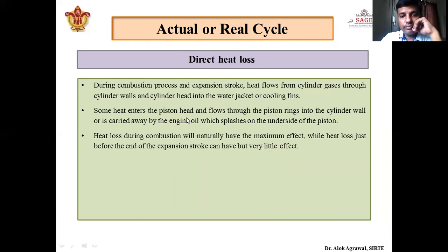And this heat loss at the starting of the power stroke or expansion stroke has the maximum effect, while the heat loss just before the end of the expansion stroke, when the expansion stroke is about to end, has the minimum effect on the overall output of the engine. At the beginning of the power stroke, whatever amount of heat is rejected has maximum effect, because that heat could be converted into work.